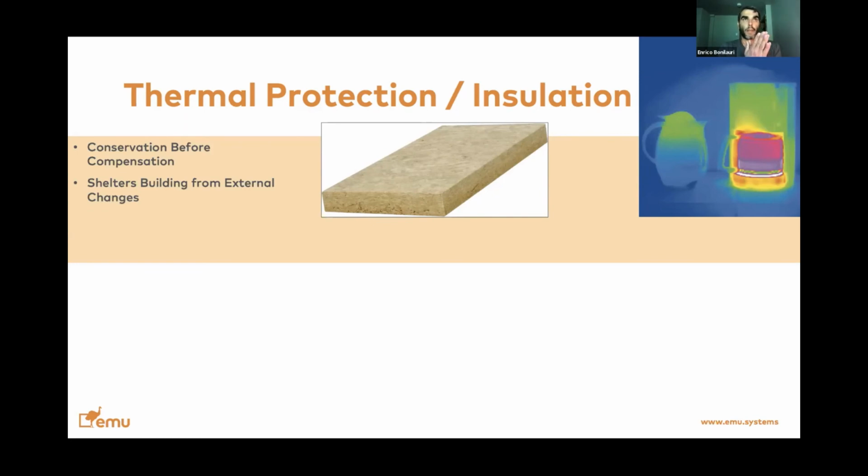If you have a winter blizzard or a heat wave in the summertime, if your building is considerably more insulated, then it becomes extremely more resilient. If the power goes out, your insulation does not stop working. You are still protected. And we'll see at the end of this presentation a test that we carry out in the workshop that we do in teaching builders, and how we prove this concept of thermal resiliency by having a very highly insulated building and letting it out of power overnight.